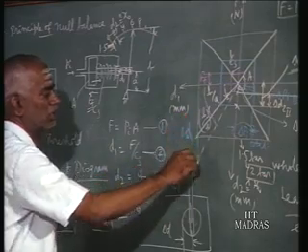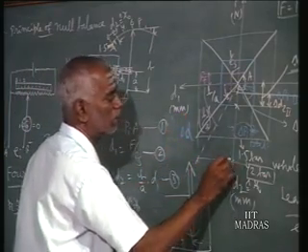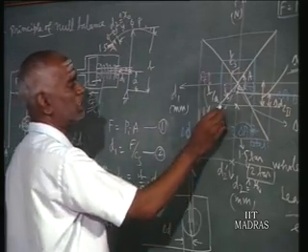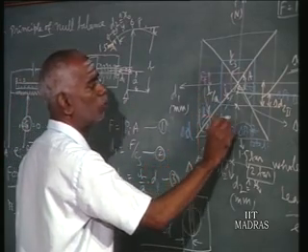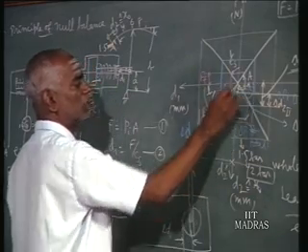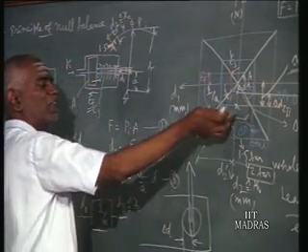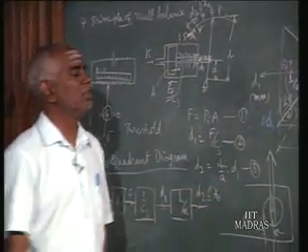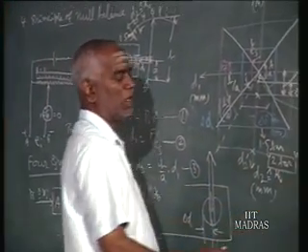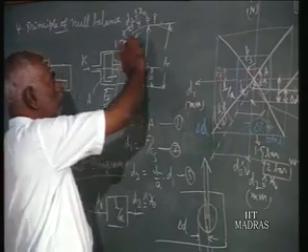So now this is the same. Now you find you got another, this is your d2 dash. Since it is increased, you will find the corresponding output displacement is increased to a larger extent. Now see whether it is more than 1.5 mm. So the 4-quadrant diagram we are making use of, not only for fixing the least count, but also we can check whether there is 1.5 mm.